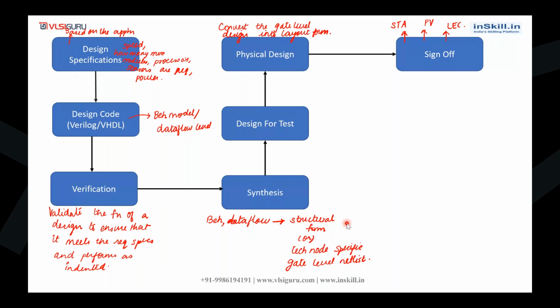So in the process of chip design, our design is undergoing a lot of changes in each and every stage. That's why LEC is done to check whether the final design is logically equivalent to the original design or not. Actually LEC will be done after each stage, like after synthesis, after DFT, after PD. Okay.